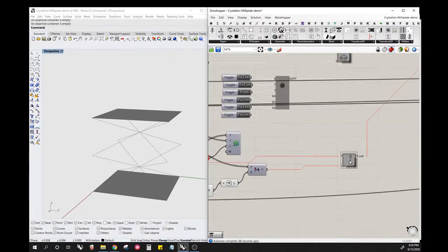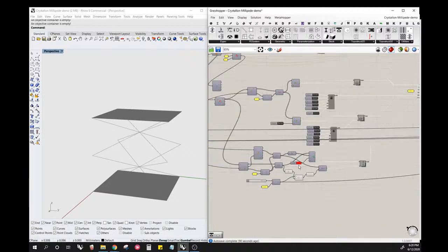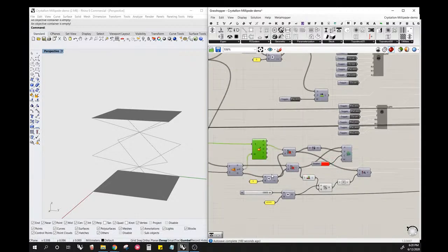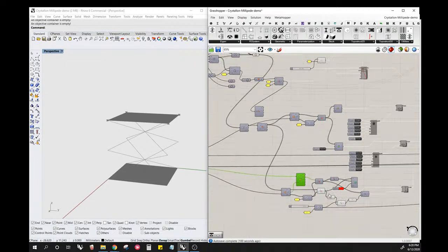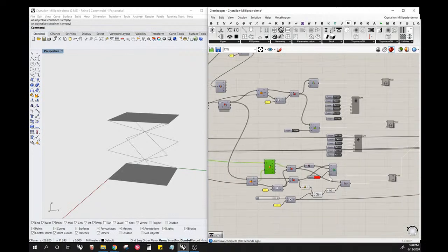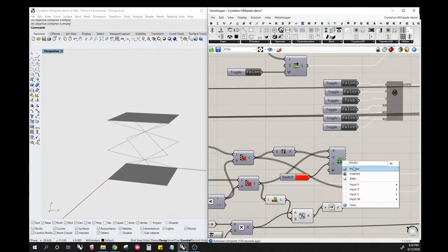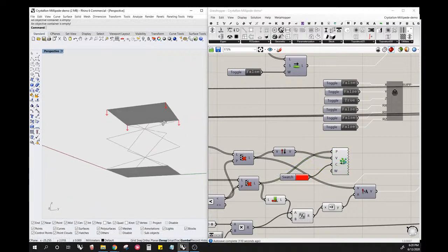And lastly, loads I set up pretty much the same way. Loads, you need a location of the load, and then the load is actually just a vector. So you create a vector which is a direction, and the amplitude is the amount of force in newtons. So what I've done is actually just found those points that are touching this top surface, these here. And then for the vector, the direction I want, I just made them normal to the surface.